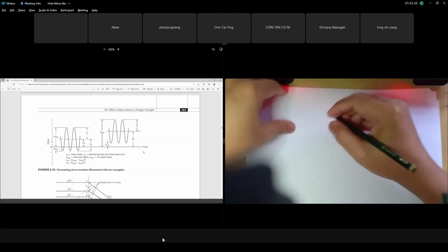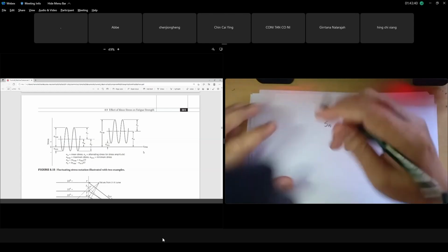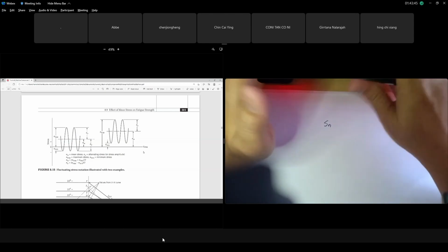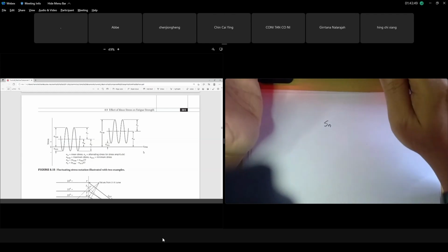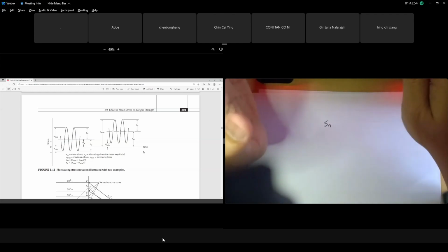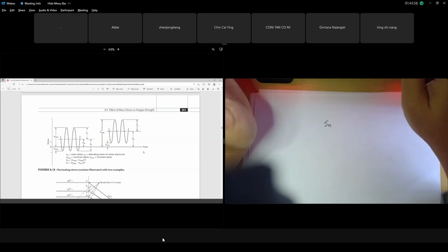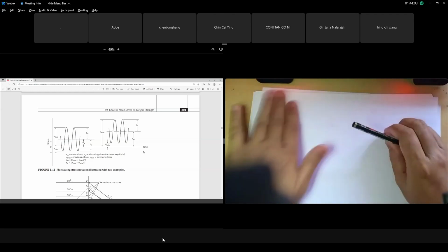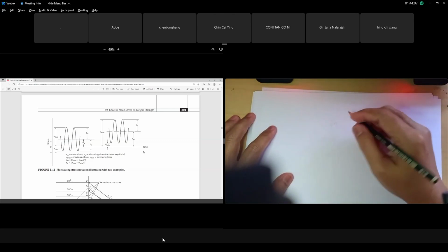But the point is, why do we need to calculate SN? I said SN is the strength of the specimen that you do analysis on, because we no longer use SY. Remember, the basic equation: your SN, the endurance limit that you calculate, over your sigma equivalent, your equivalent stress. But for fatigue it is not like that actually, because I was talking about the rough equation. Look here, class. Your safety factor is this. More accurate is this. There is a reason, later I will explain to you.